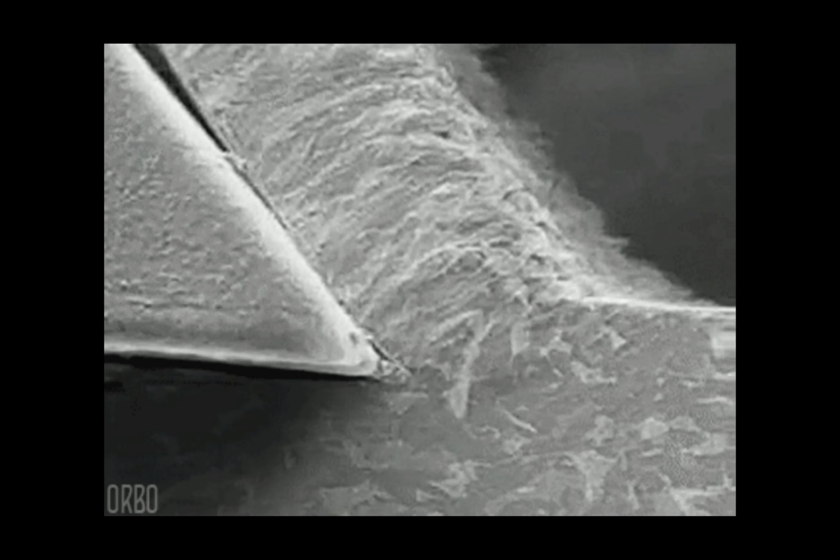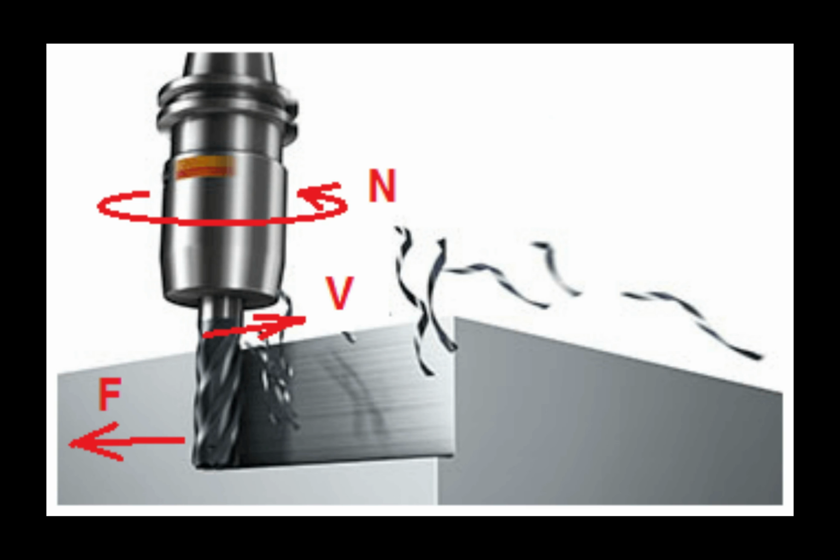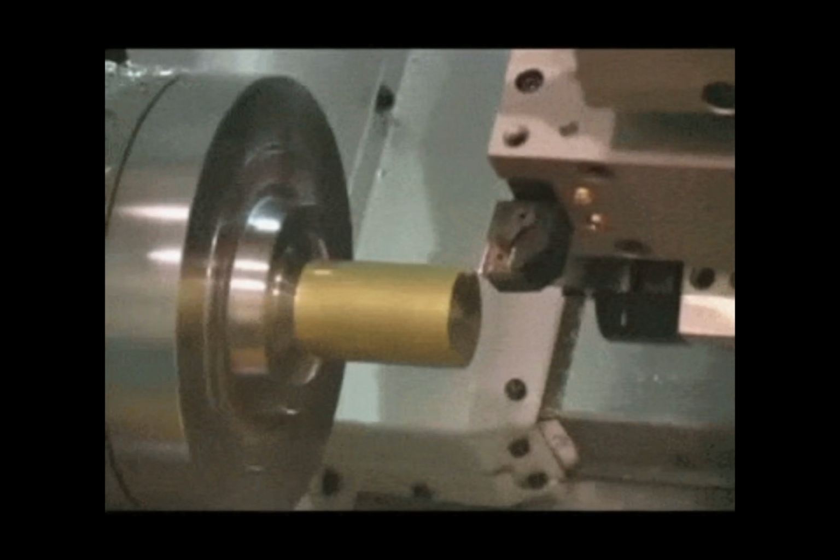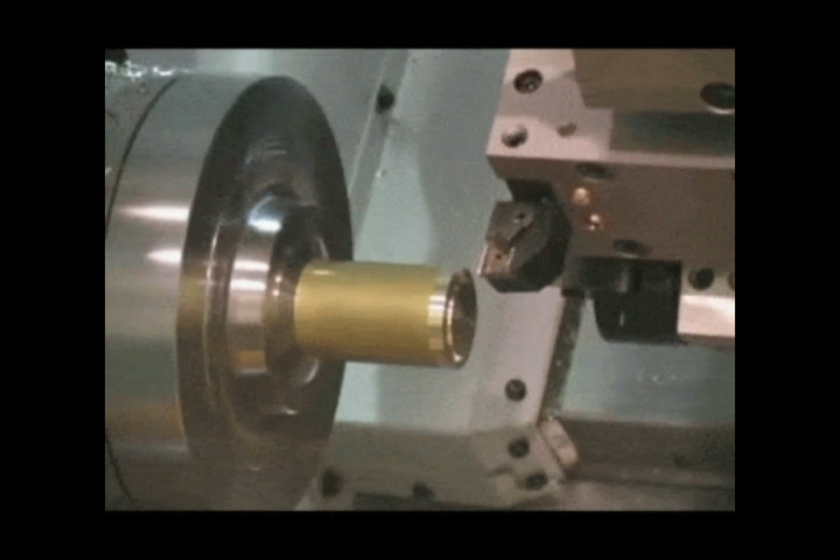Material is cut when a tool which is harder than the material has a high amount of relative motion. This motion is achieved by primary motion, called cutting speed, showed as N, and secondary motion, called feed, showed as F. The three main operations of machines are turning, where the material is rotating and the cutting tool feeds, drilling,